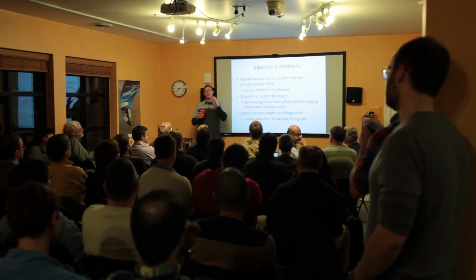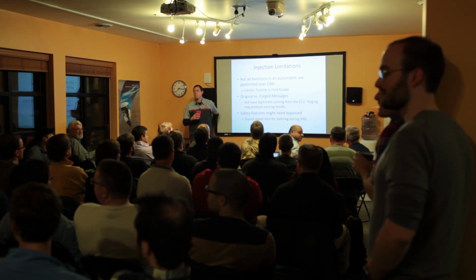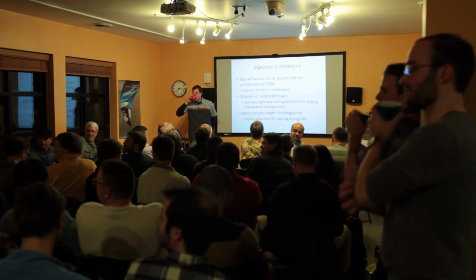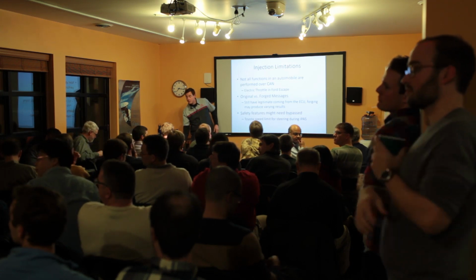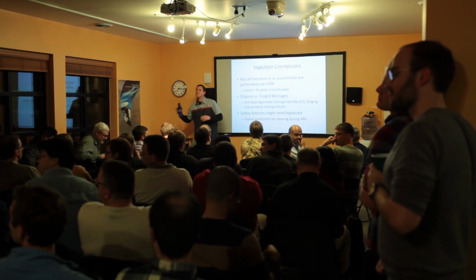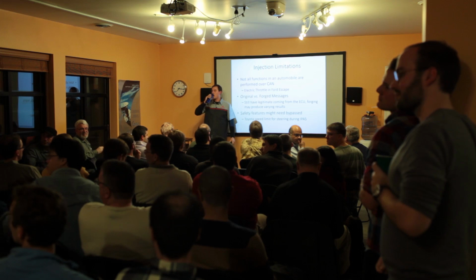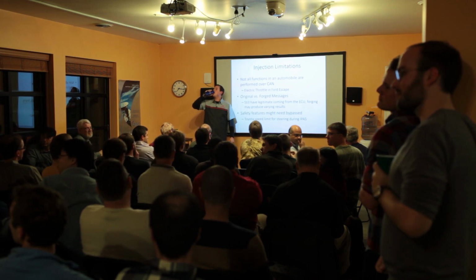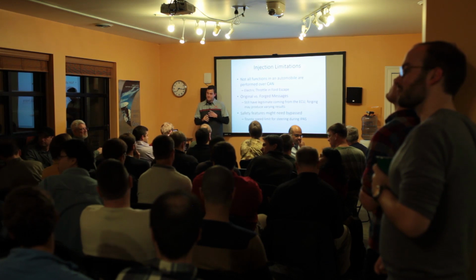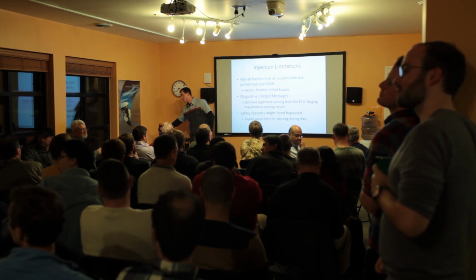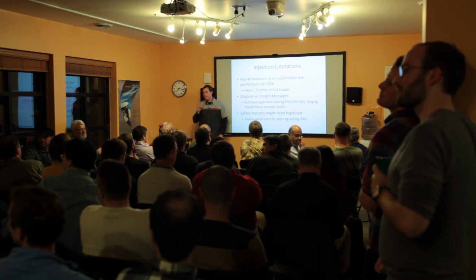I have all these memorized, which is almost how this actually works. So the reason lower is higher priority is everyone has pull-up resistors on the bus. So 1 is passive and 0 is active. If at any time you're watching what you transmit, if at any time you see yourself transmit a 1 and there's a 0 on the bus, you just lost. Yep. So you back off.